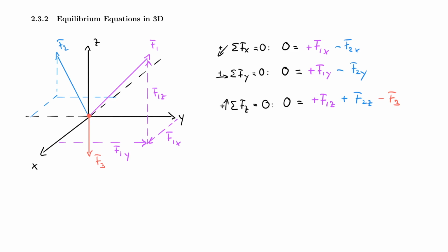And I say that again so that you develop a good 3D understanding of these problems. So to move from this point to the end of F1, you can either go along F1, or you can, for example, go to the right first, then out of the plane, and then upwards. And that's how you assign the proper directions here. And that is important so that you understand where the plus and the minus is coming from.